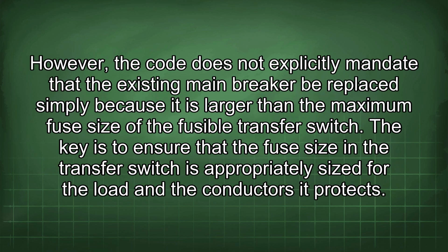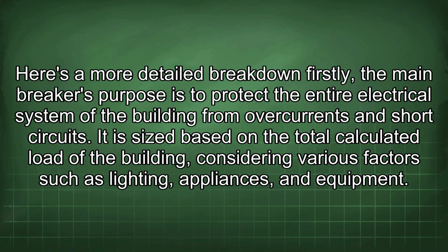However, the code does not explicitly mandate that the existing main breaker be replaced simply because it is larger than the maximum fuse size of the fusible transfer switch. The key is to ensure that the fuse size in the transfer switch is appropriately sized for the load and the conductors it protects. Here's a more detailed breakdown.